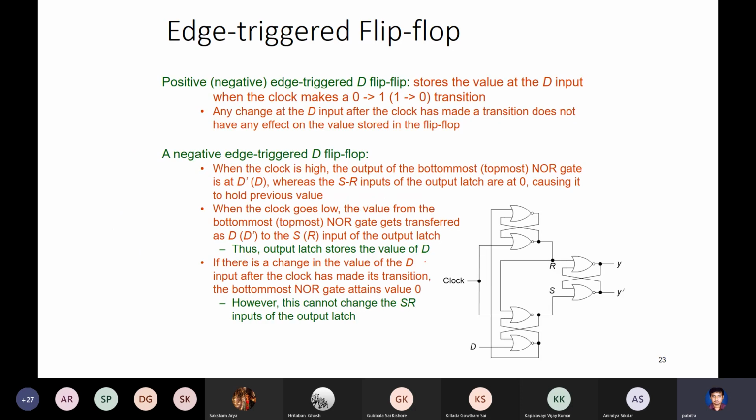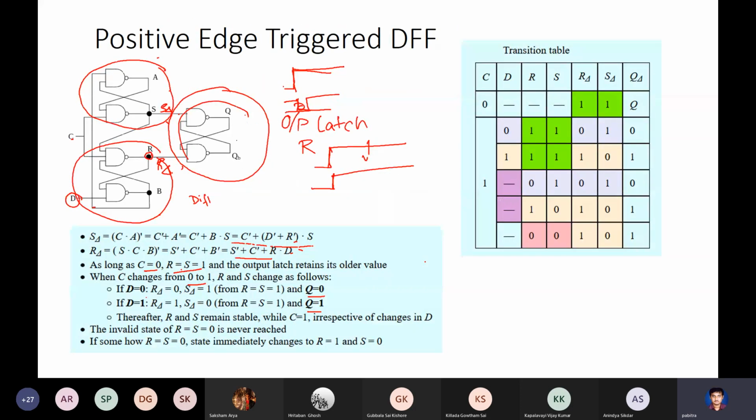Okay, so with this I end this. Next class we'll go into the design of more complex circuits. So we have studied basic latches, 4 types. Then with an enabling input, where we put a clock, it's a clocked latch, which we call a flip-flop. We can have further circuits to surpass the problems of stability and multiple changes in an enabling clock cycle by having either edge triggering or master-slave combination. We have seen their combinations, and all these circuits you can analyze either by the excitation table or the excitation function, and you can find out their operation.